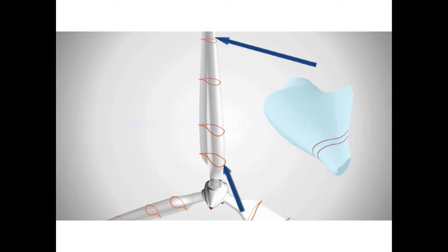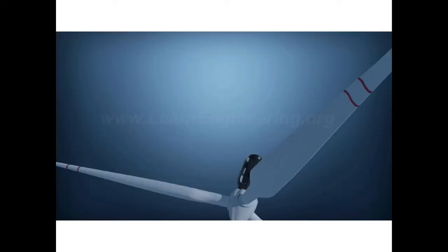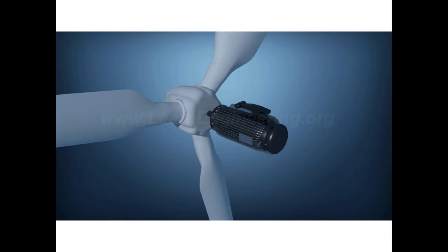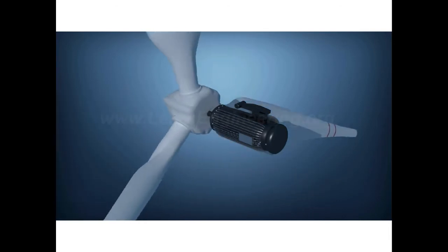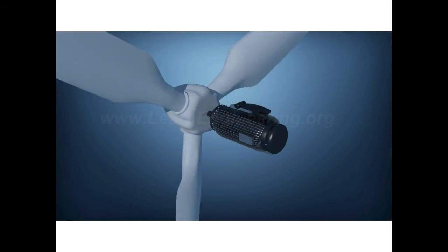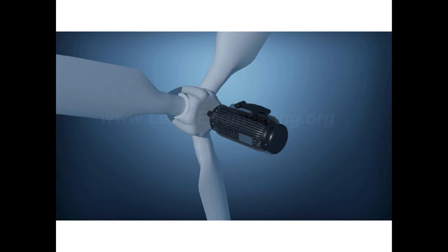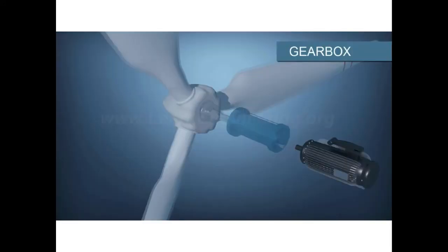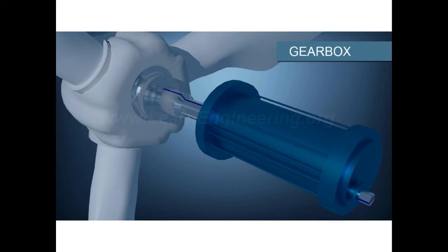However, this rotation cannot be directly coupled to a generator because the wind turbine blades typically turn at a very low rate of RPM due to the issues of noise and mechanical strength. Considering this slow speed rotation, we cannot produce any meaningful electricity frequency from the generator. So, before connecting to the generator, the speed is increased in a gearbox. The gearbox uses a planetary gear set arrangement to achieve the high-speed ratio.